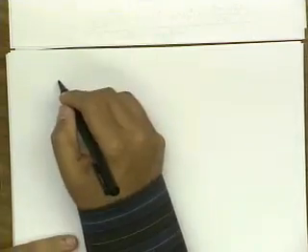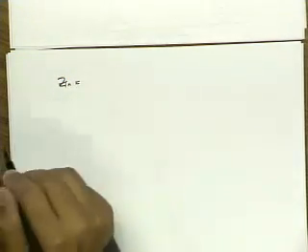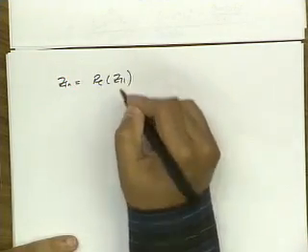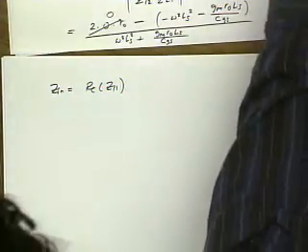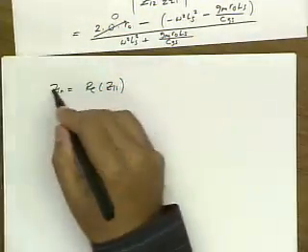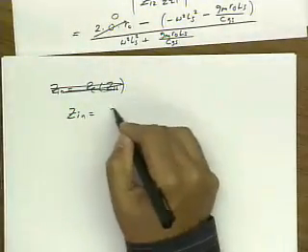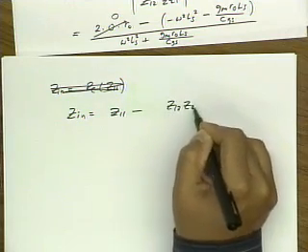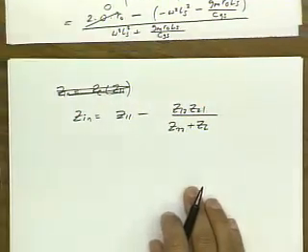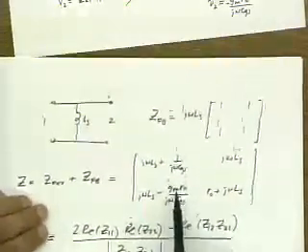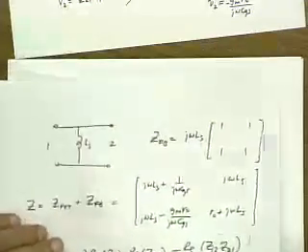All right, so let's show that this in fact is equal to the source resistance. Let me look at Zin. So Zin is the real part of Z11, right? And again, if I go back and look at my Z matrix, sorry, what am I saying? Zin is Z11 minus Z12 Z21 divided by Z22 plus ZL. Okay, so now if I go back and look at this matrix, I can just substitute here.